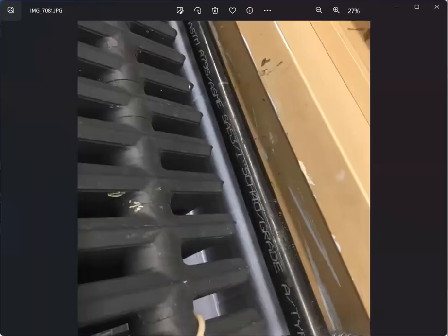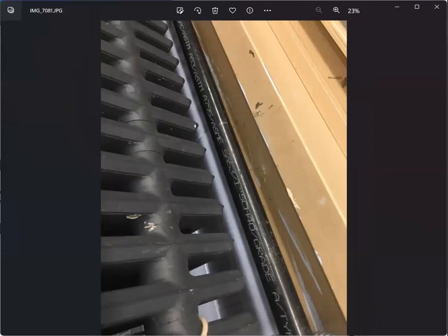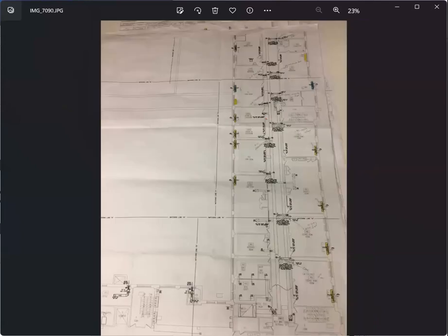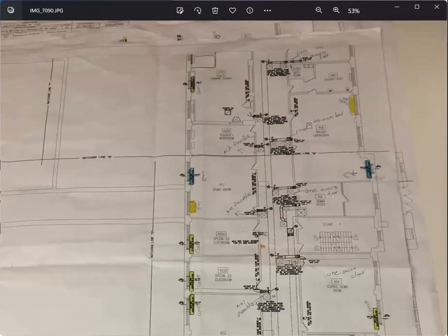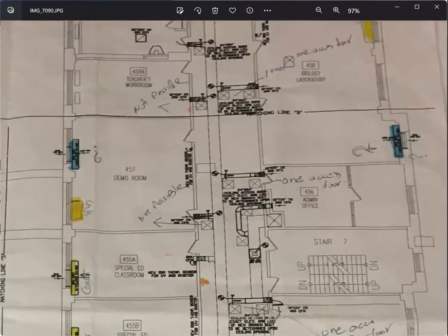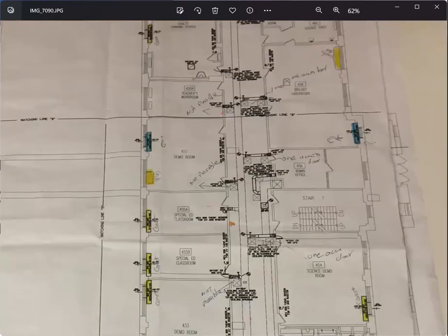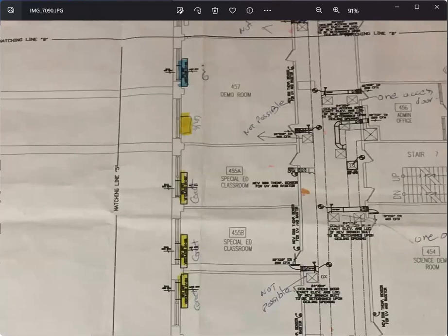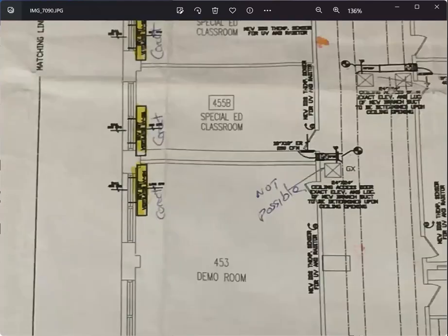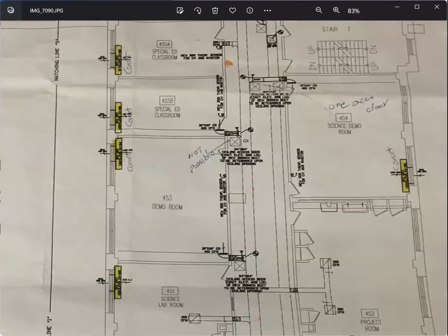40, Grade A. Sometimes you're going to see that in the drawing notes, material specifications. You need to confirm the materials that they're using, if it's according to the drawing. And this is the drawing plan. This is the walkthrough that I make, and those are the units that I have installed, and take a photo of each equipment tag ID. So each one of these is labeled with 1000 CFM on the shop drawing.